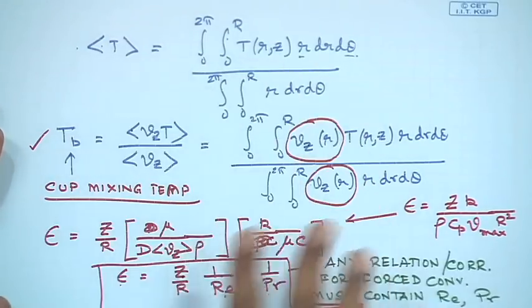So, through a simplified analysis, we have shown how the temperature profile for flow through a tube with uniform heat flux at the tube wall can be expressed, the governing equation, through the use of energy equation. We identified the boundary condition, we non-dimensionalized the equation, and we have seen that a closed form solution can be obtained if we use a large axial location assumption.